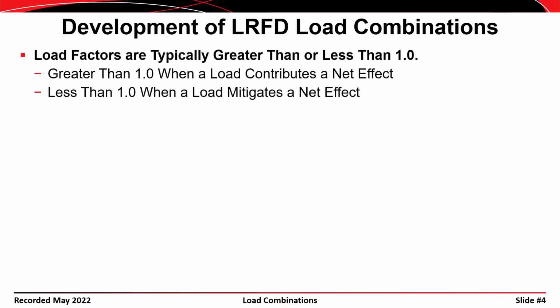So the load factors that we develop are typically going to be either greater than or less than 1. If a load effect is leading to the design of the member, making the demand worse, then the load factor is typically greater than 1. If the load effect is helping the member, making the load demand lighter, then the load factor is often less than 1.